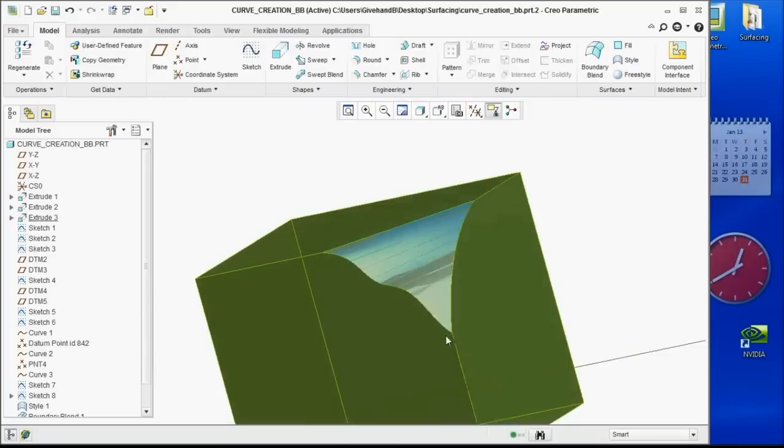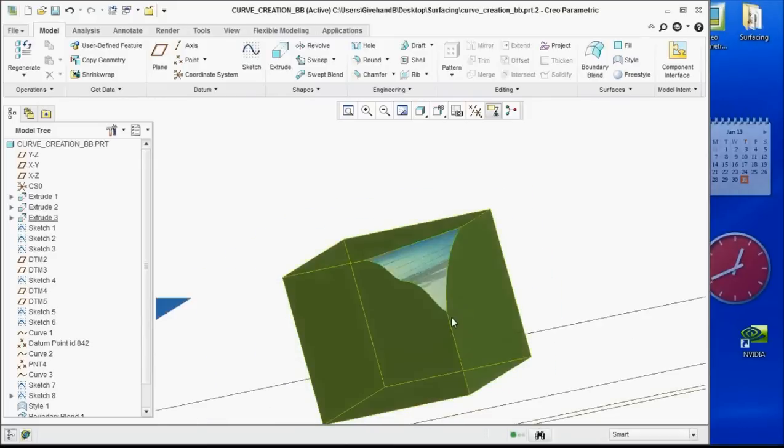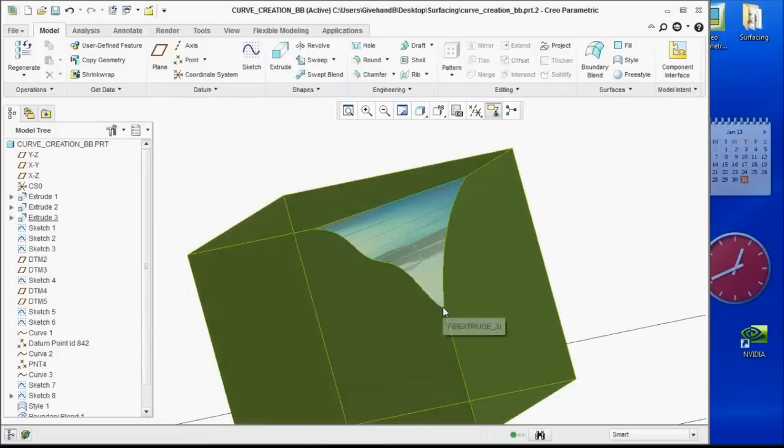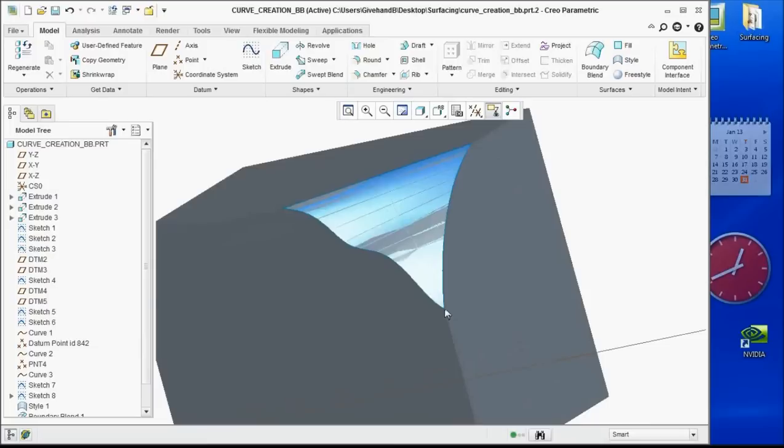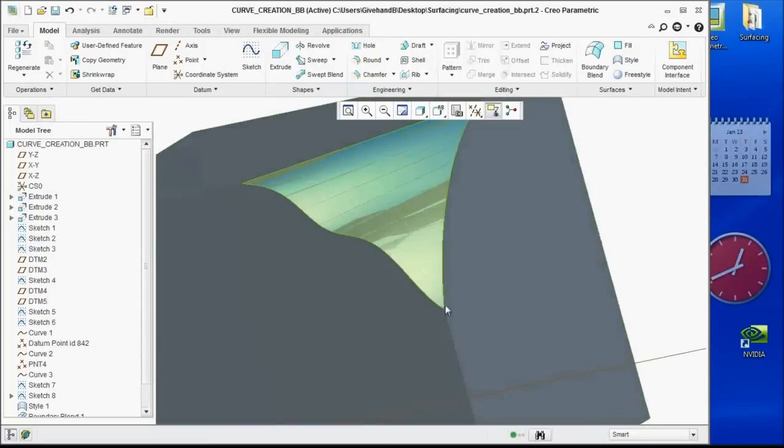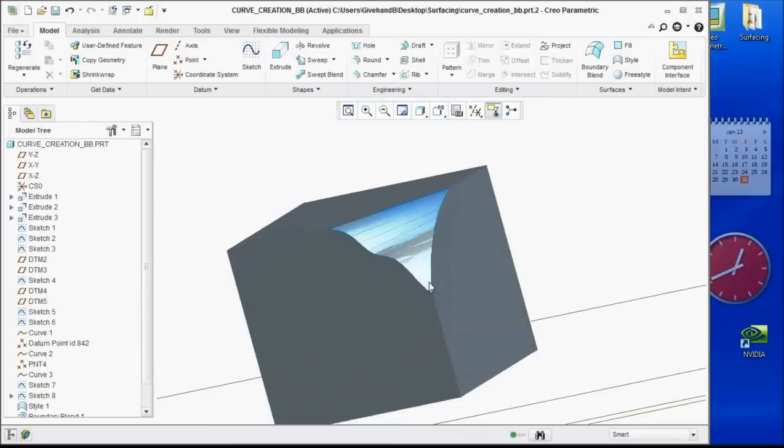And yes, you can create a surface from that, but when you go to solidify or thicken that, it goes down the toilet quickly, okay? So something that I picked up over the years is that if you have a straight line right here, this works much, much better, not for the surface creation, but for when you go to solidify or thicken that, so all of a sudden you don't have this weird geometry driving it to the corner, and you have to deal with that.